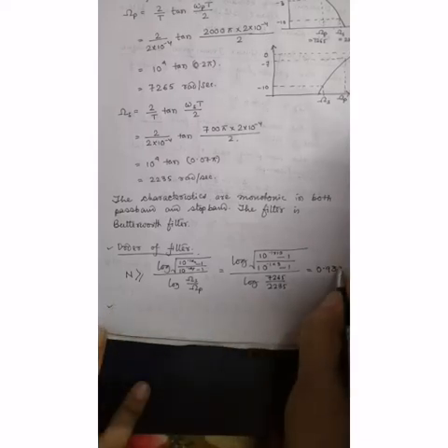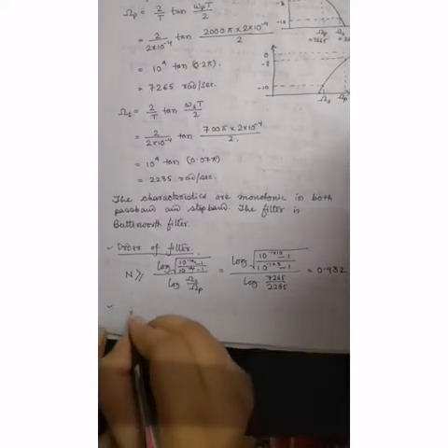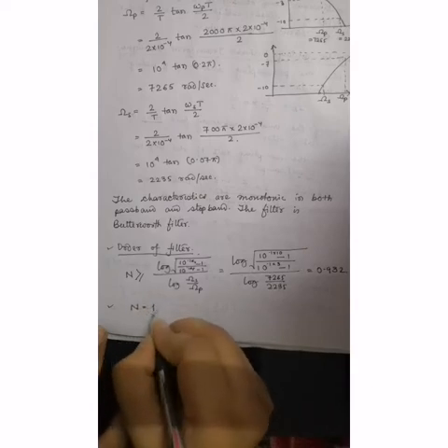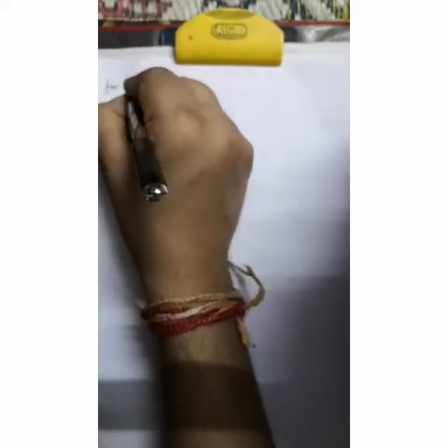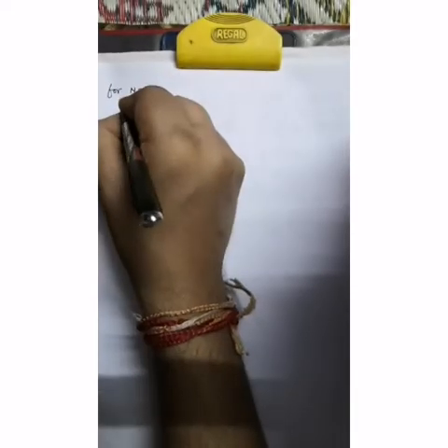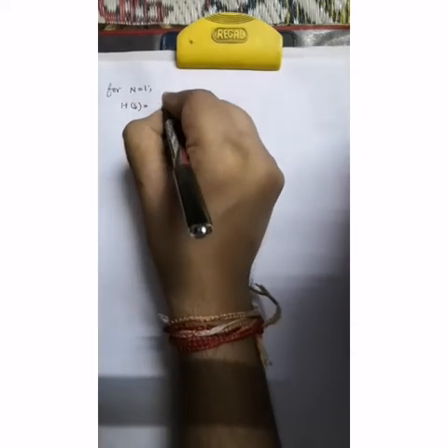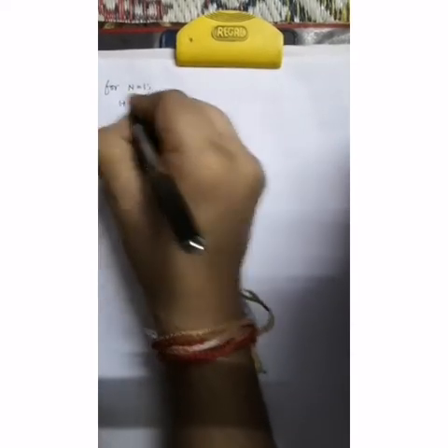The second step is round off to the next higher order integer. That means n becomes 1. So for the value of n equal to 1, you have to find the value of Hs. From the previous table in the class of Butterworth filter, we already discussed, if the value of n is 1, 2, 3, 4 like this, what should be the value of the numerator and denominator? The numerator value is 1 fixed, and for the denominator it is changing. There is a table also there. You can just check the previous class. So for n is 1, Hs becomes 1 by s plus 1.